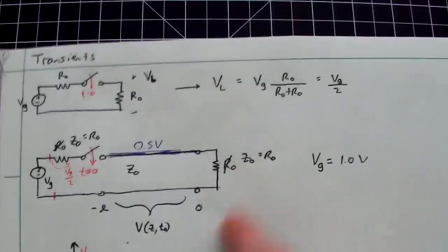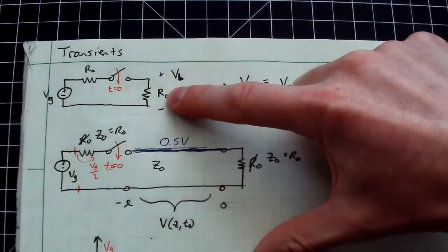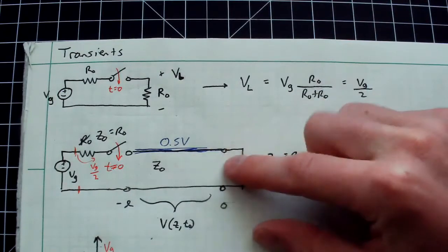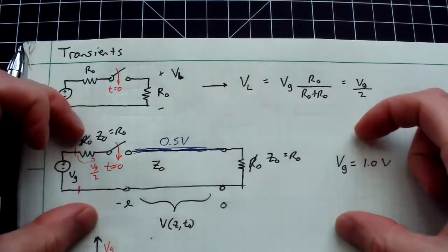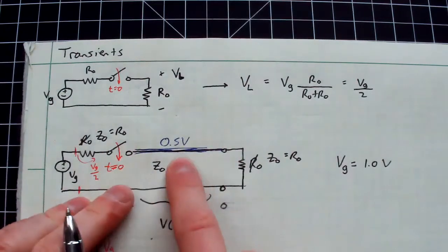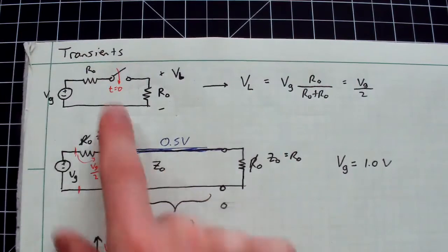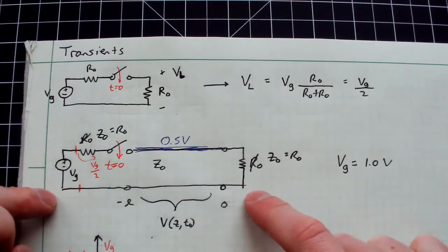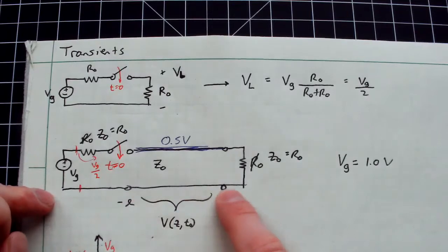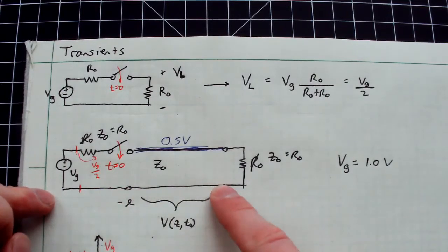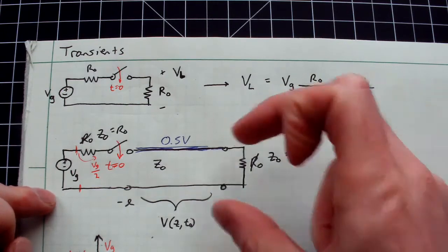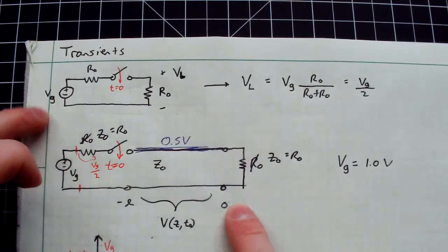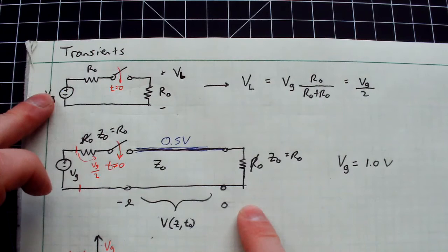And that's what you would expect, because for all practical purposes, this circuit is the exact same as this circuit. It's just a shorted line here with some finite characteristic impedance. And after infinite time has passed and there's no more transients, you can think of this as simply a short circuit here between these two nodes. So in your mind, these are kind of the same circuit. The only difference is the transmission line model accounted for the fact that there was some propagation delay for that voltage to reach the load. But whether this is a kilometer long or 7 inches or 5 millimeters, this same effect will happen. And these circuits should stabilize to roughly the same thing after a bunch of time has gone by.